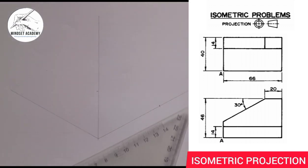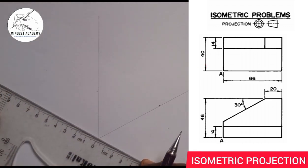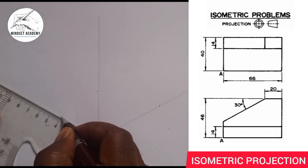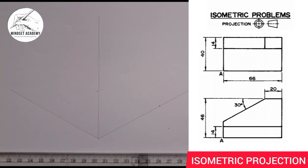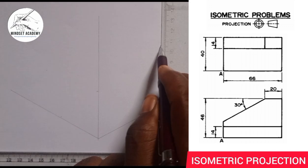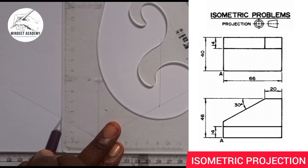And the width is given to be what? 40, you get from the plan, and it's 40. So I'll measure 40 here, from 0 to 40. Then I'm going to project all those points up over this way. Come here too, do the same thing.